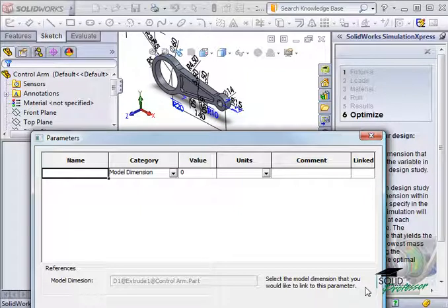The first step is to specify a single dimension to adjust to try and reach the factor of safety I'm looking for. One limitation to optimization using SimulationXpress is that you can only optimize one dimension at a time, based on the part's strength in a static loading test. Full versions of simulation have virtually unlimited possibilities for optimization that can explore vibration or buckling responses at the same time as strength across many dimensional variables, since the optimal design is often a compromise between two or more features.